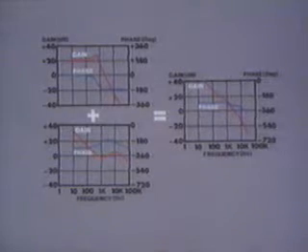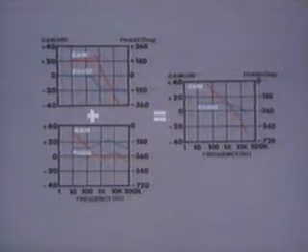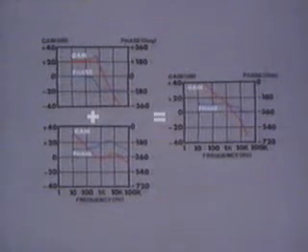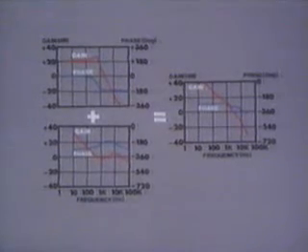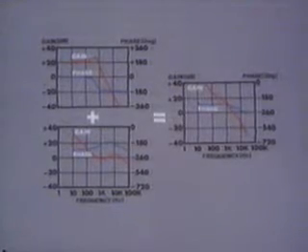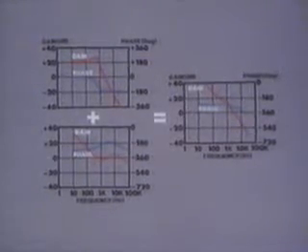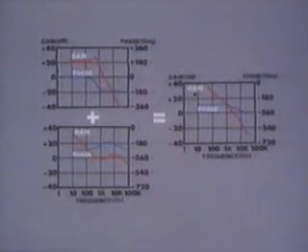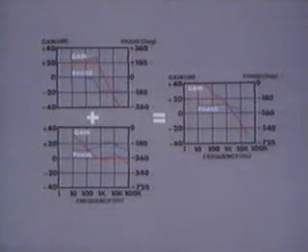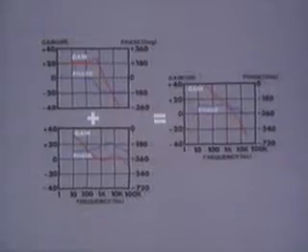The Bode plot graphically displays the transfer function, that is, the output divided by the input. The Bode plot is a graphic representation of logarithmic gain and linear phase shift versus logarithmic frequency. At some particular frequency or frequencies, the total phase shift around the loop will equal 360 degrees. This makes the returning signal indistinguishable from the original signal. If the total phase shift around the loop is 360 degrees at the same frequency at which the gain is 1, or unity, the loop will oscillate.